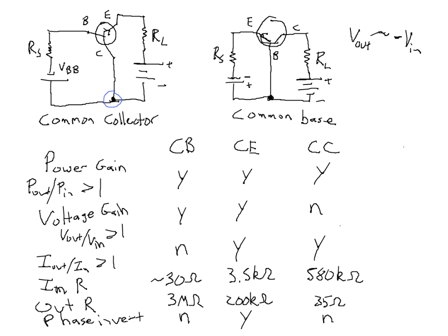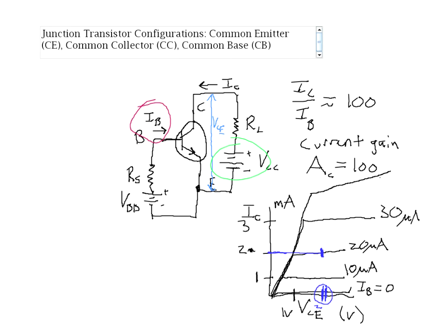And we'll learn more about what those different kinds of transistors are in later lessons. But for this lesson, what you need to remember is that there are three configurations in which one can use a bipolar junction transistor, and that each of them have advantages and disadvantages. Also, you should be able to interpret the characteristic curve diagram, VCE versus IC, for multiple values of base current. And that ends the lesson.